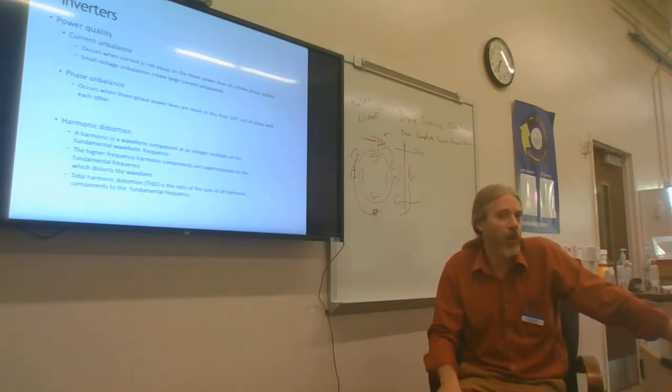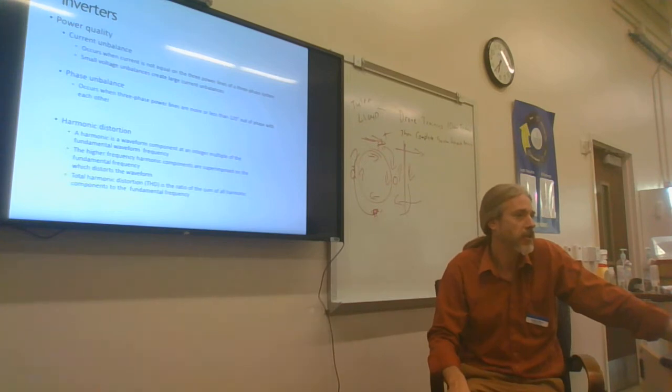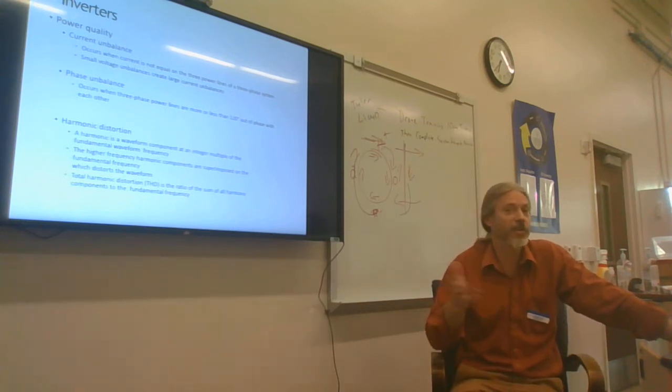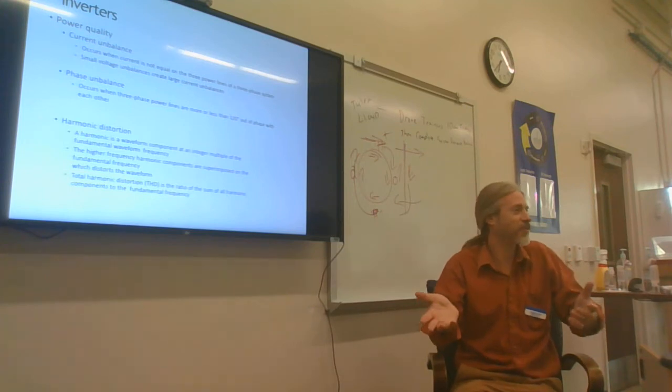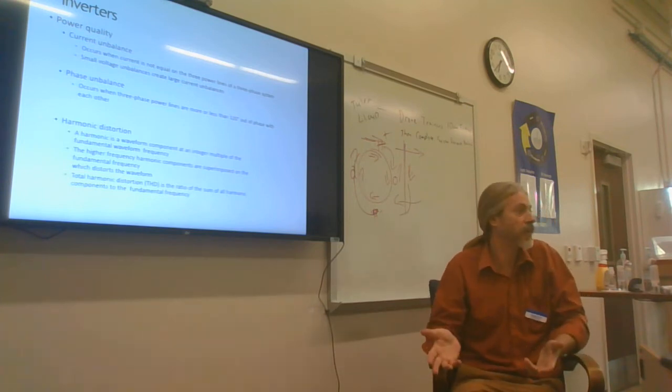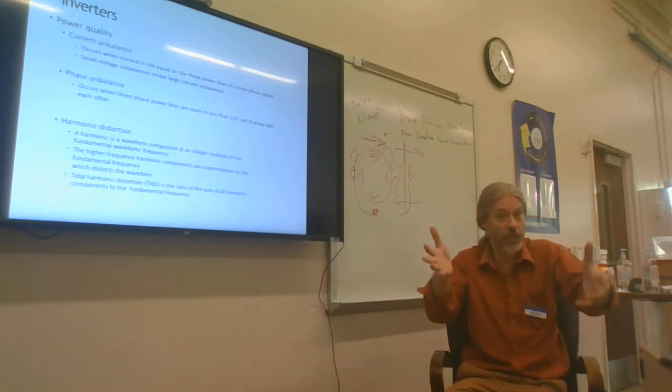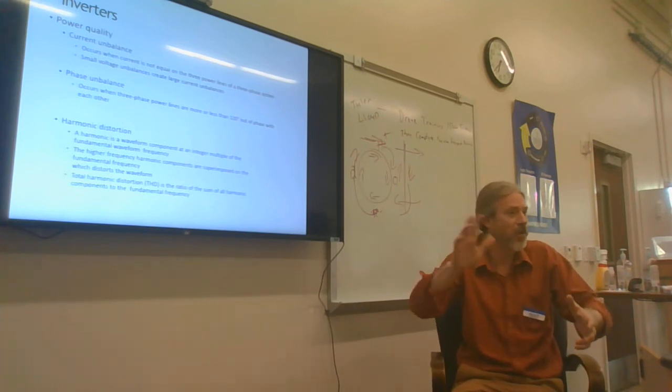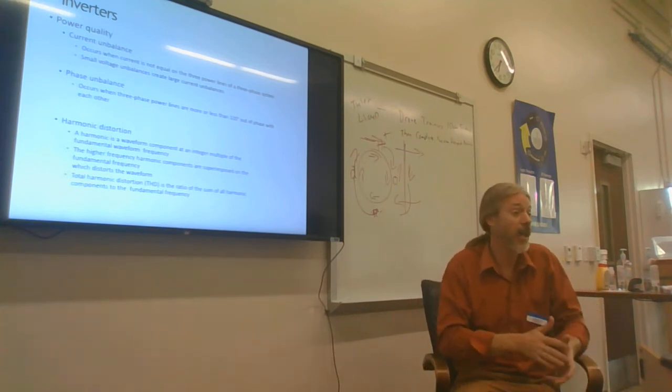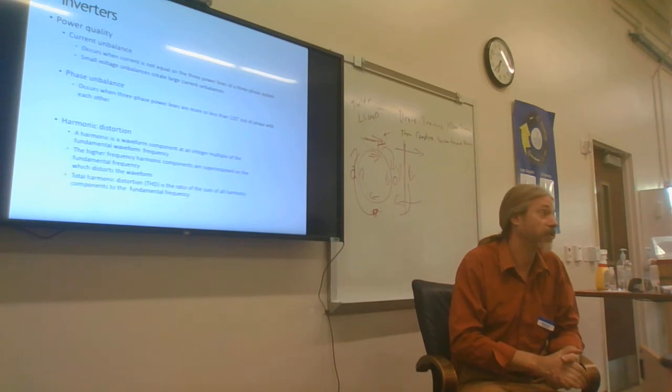If I have a voltage difference, won't I automatically have a current difference? Yeah, unless magically the resistance has varied to change that. But if all things are the same, I got a 3-phase motor, I got a higher voltage on one of these 3 phases, that means I'm going to have a higher current on one of those 3 phases also.